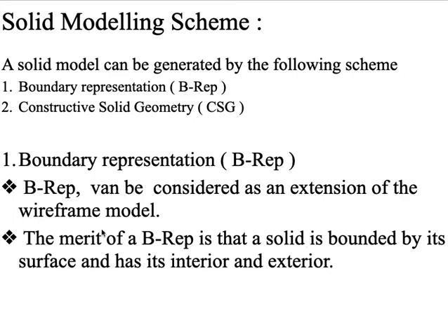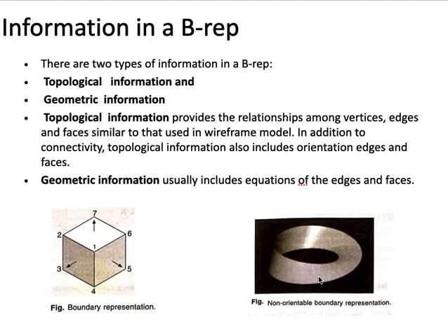Here, the boundary representation, B-rep for short, can be considered an extension of the wireframe model. The merit of B-rep is that a solid is bounded by its surface and has its interior and exterior. The surface of the model consists of a set of well organized faces.